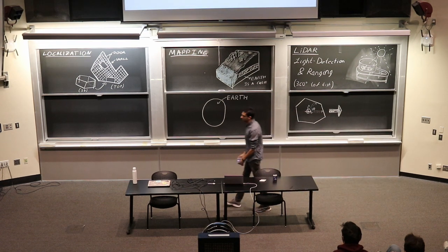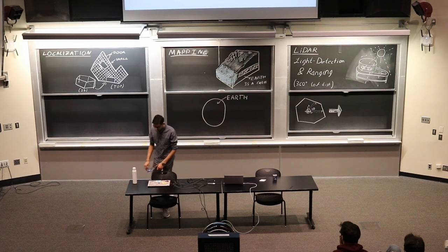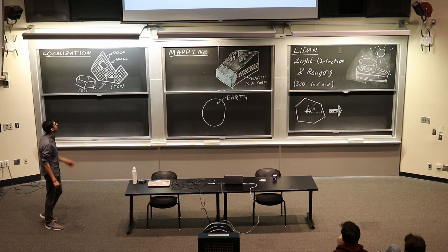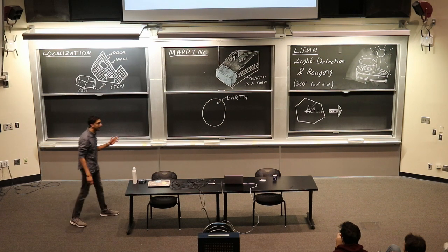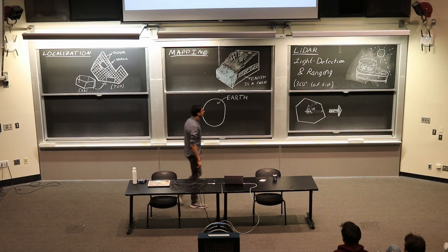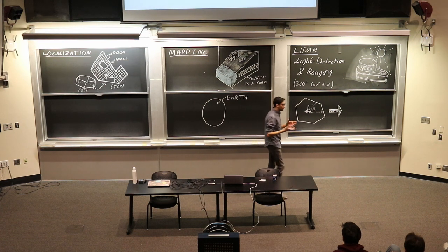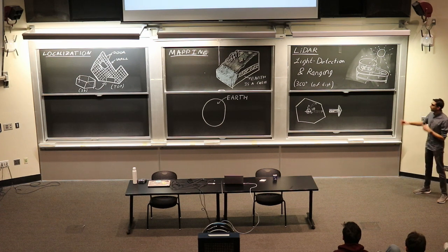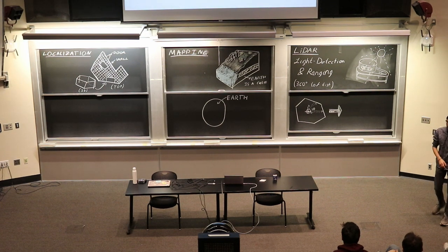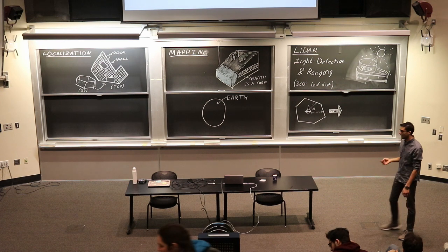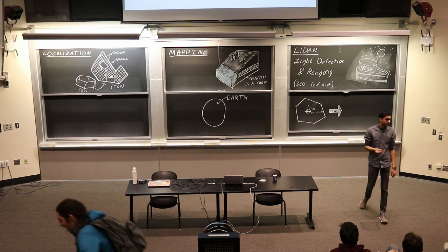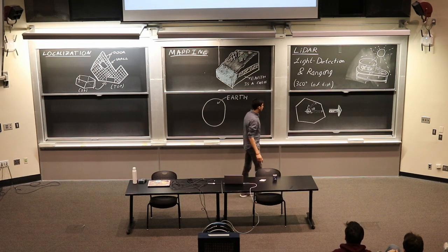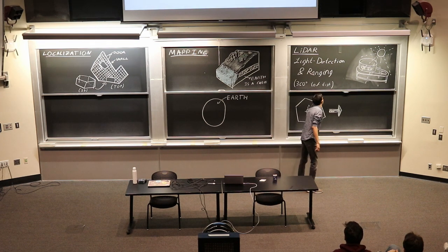Yeah. So the first thing we're going to go through is LiDAR. What is LiDAR and why you care about LiDAR and why it's like the greatest thing since things were things. So a LiDAR, you're going to find a LiDAR in your kit we gave you from MASLAB. And a LiDAR stands for light detection and ranging, and that's a really fancy way of saying it's a 360-degree distance sensor. All a LiDAR really does is, so actually first let's talk about what a time of flight distance